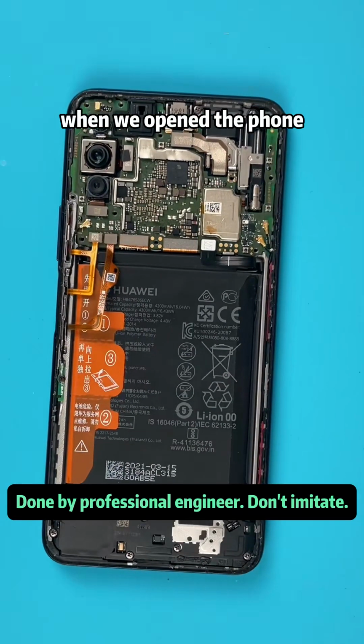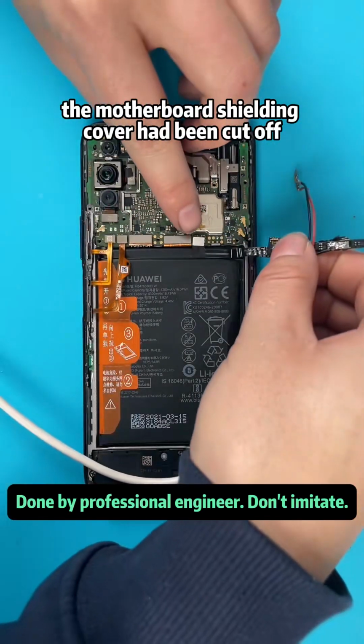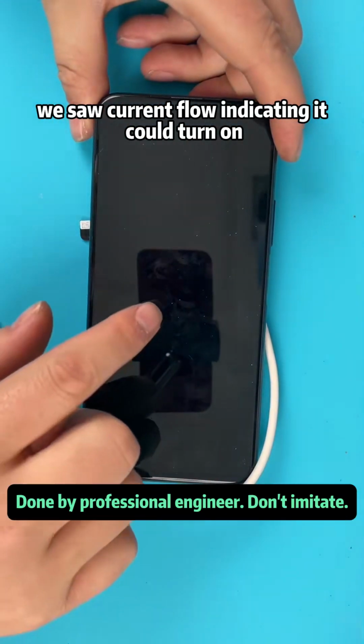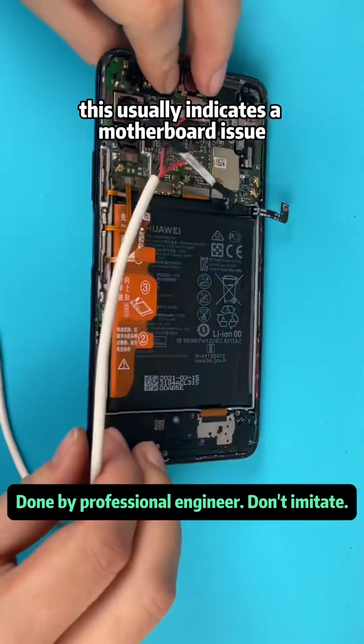When we opened the phone, we saw it had indeed been repaired before. The motherboard shielding cover had been cut off. We connected the power meter for testing. After pressing the power button, we saw current flow, indicating it could turn on, but the screen wasn't displaying anything. This usually indicates a motherboard issue.